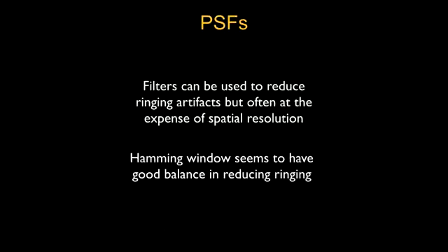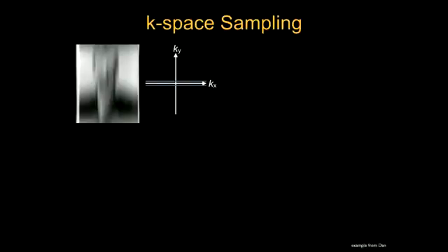But in many cases, the Hamming window seems to be a good balance between the ringing and losing the resolution. People look at the balance between the two and the trade-off, and the Hamming window happens to do a good job of balancing these two.